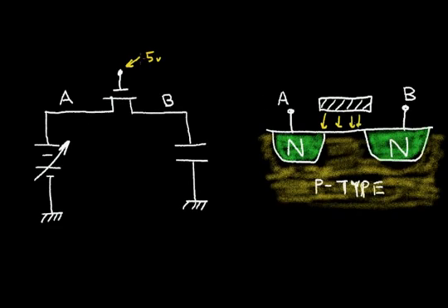Here, and it'll form a channel region. It'll cause conduction between point A and point B. Now when this gate is set at 0 volts, the switch will be off. I'll have no electric field, I'll have no channel in the FET transistor.